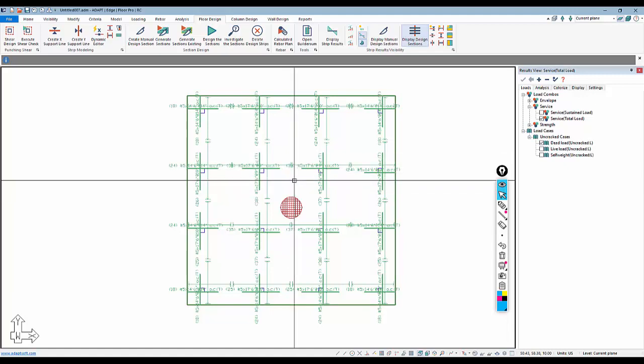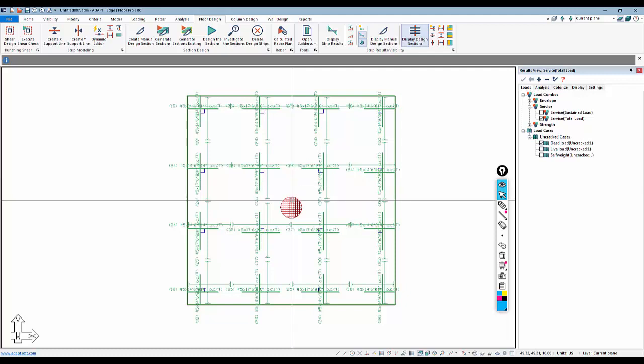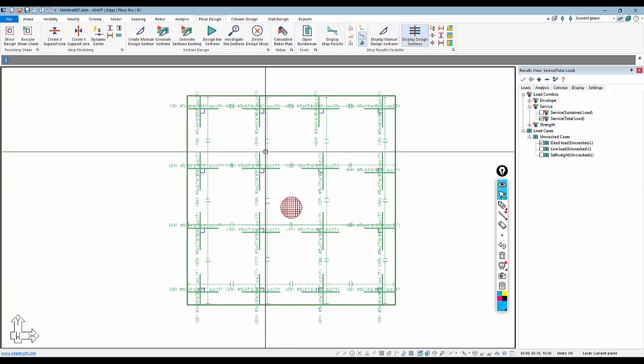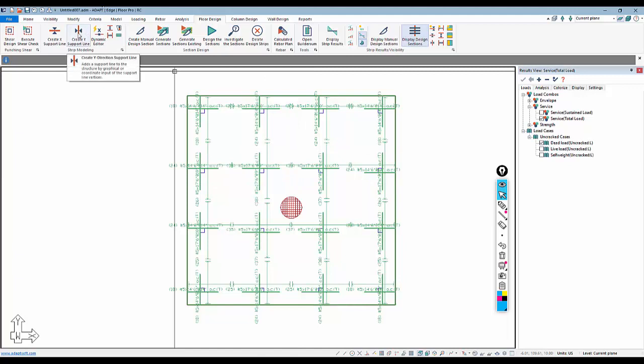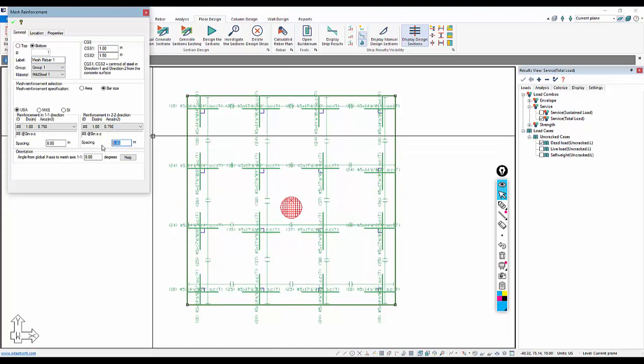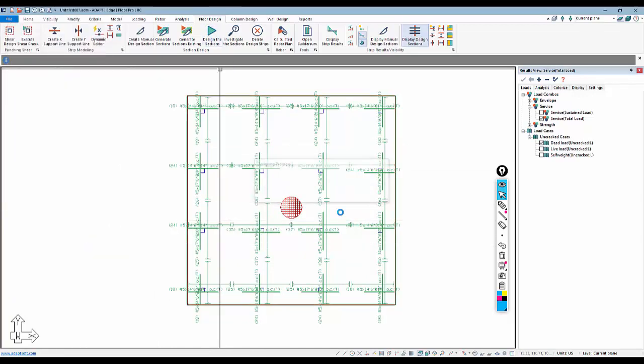We needed 6 square inches previous. This is enough to handle the 6 square inches. So because there's no rebar required for service or strength, the program doesn't check the spacing, even though it's set to not disregarded. If I loosen up this spacing a bit, maybe I go to 12 square inches, and I redesign the cuts,